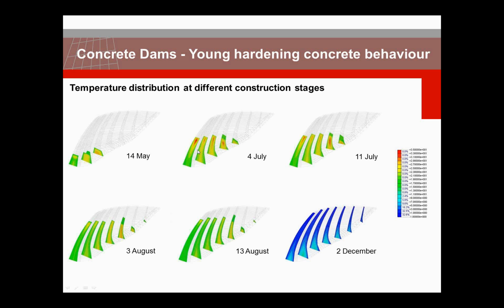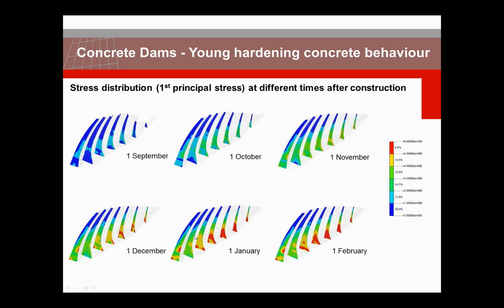The colors represent the temperature at this date inside the dam. So the outside also varies, because the outside temperature is defined by the environment temperature, whereas the interior of the dam usually shows higher temperature because of the heat generation. And with time, this heat in the dam will reduce because the heat will flow out of the model to the environment.